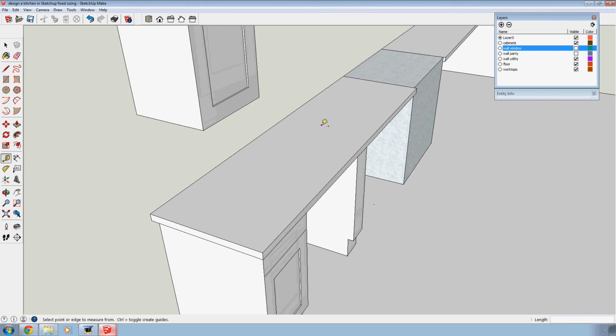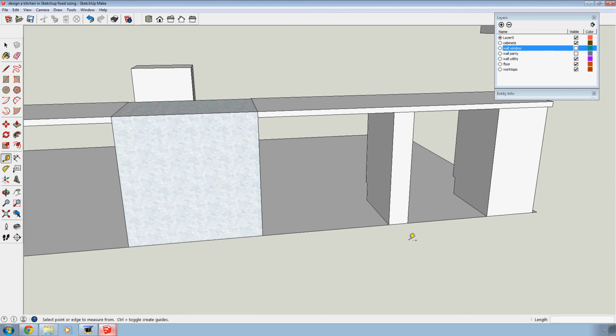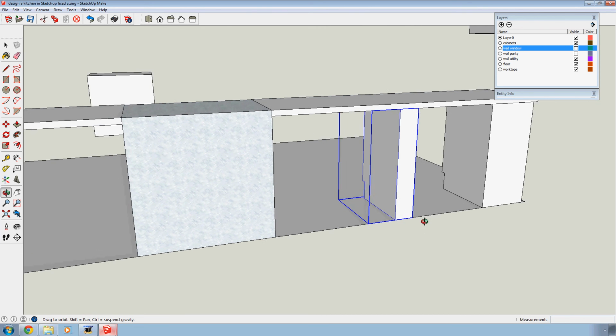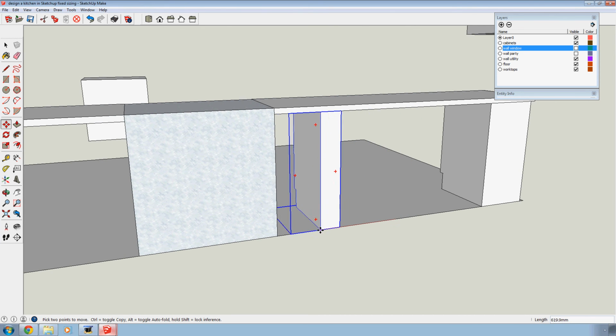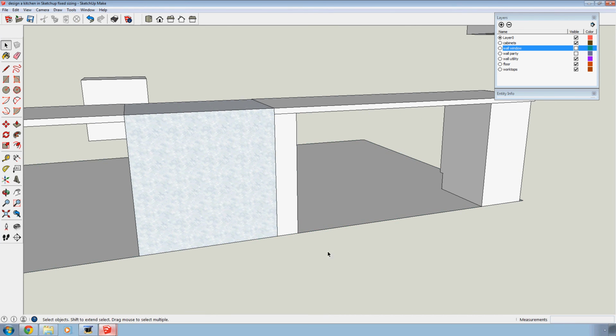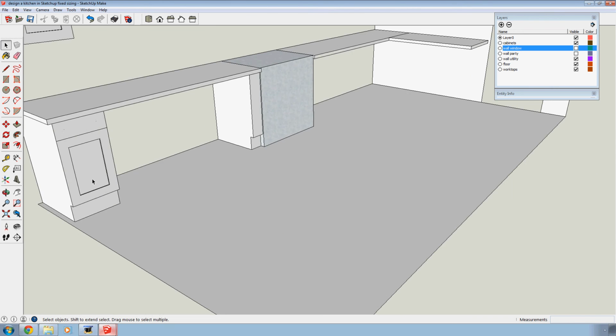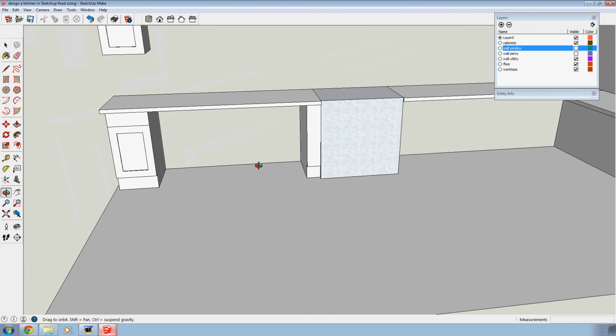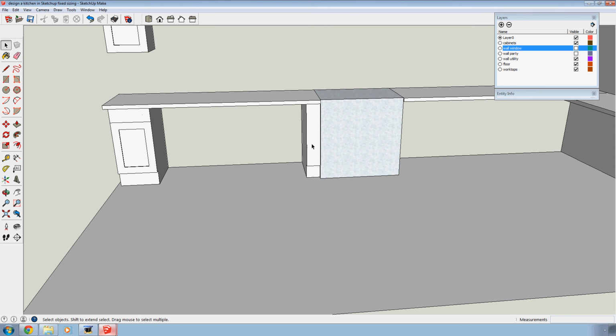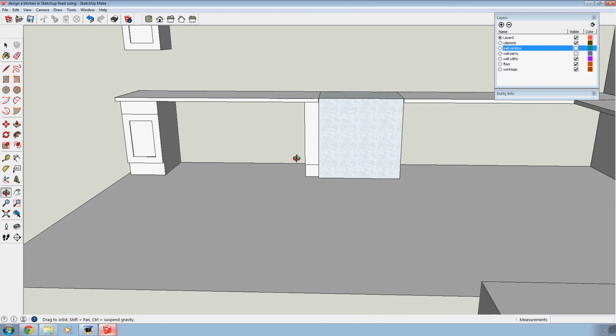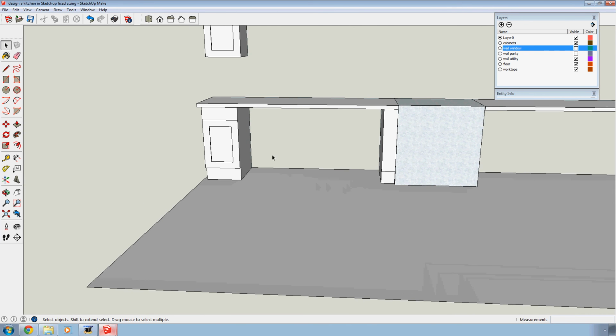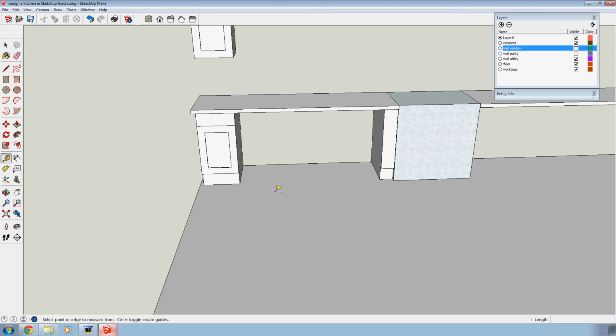We'll take the window wall off so we can see what we do. It's quite likely that if you're trying to keep the symmetricality going, then you're going to end up with one of those units on the other side as well. So now if my calculations are right, this space should now be 1600, which will obviously divide nicely into 800. So let's enter 800 here.